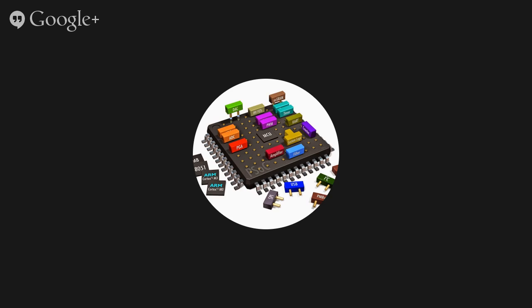But this is pretty brute force, just with some code and a CPU. That's not really anything special, so I don't want to do that. I want to do something a little bit more sophisticated. So let's say I want to drive this LED with a PWM. I'm going to go back to my schematic here, open up my configuration tool for the LED, and re-click on this hardware connection. Then we're going to come over here to the Cypress components.